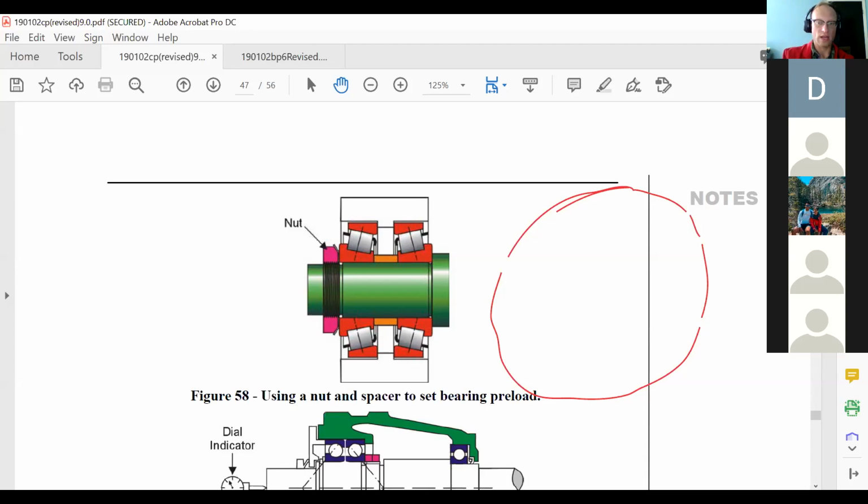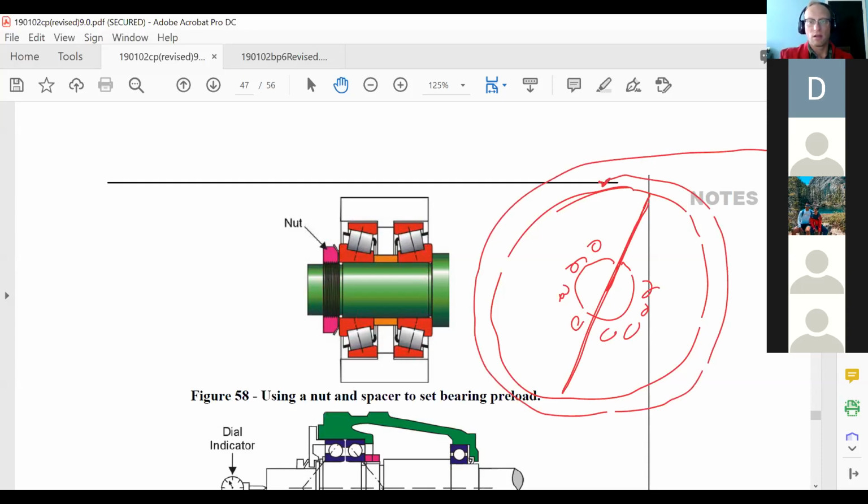And when you're measuring it, they actually know. So you're measuring the preload on a bearing that's on a shaft here, okay? They know the radius and the diameter of the component you're measuring. What you actually do is you pull it and take your value, and then you calculate torque based on this distance here and this force, right? Because it's how many pounds and how many feet or inches, and I can get torque. They want you to figure that out and calculate that, and they already know how much this is, so they know what number you're looking for, and they know if you're within that range that everything's good, and if you're not, then something was misadjusted. Make sense?